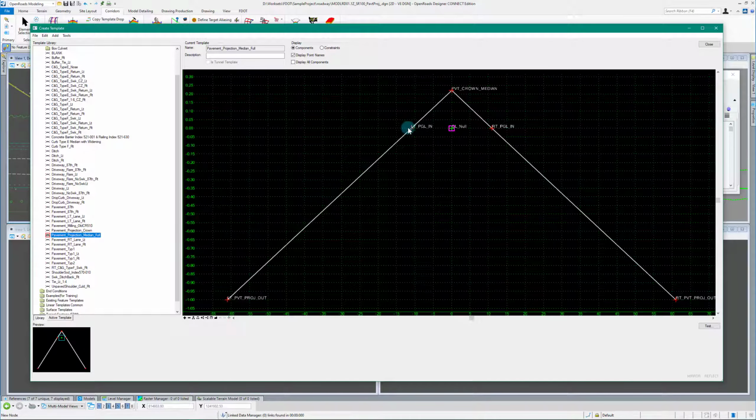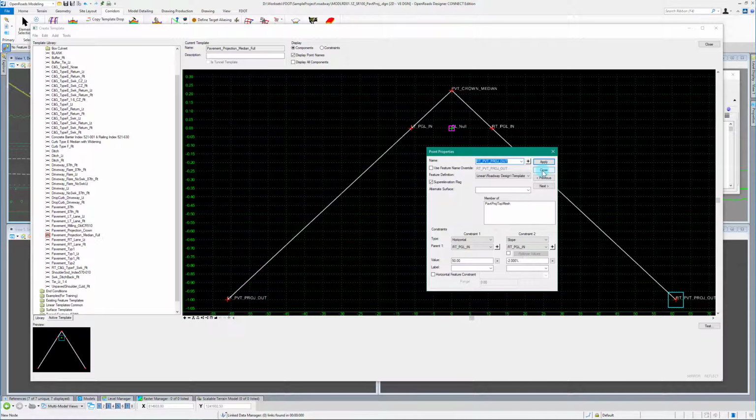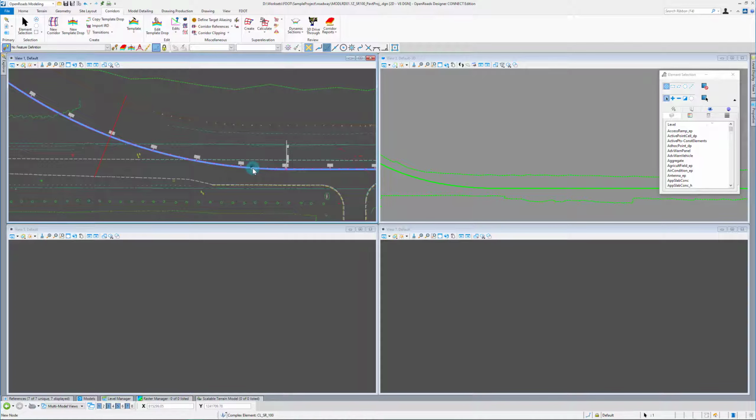And these are also able to be adjusted depending on super elevation. So if I wanted to do that, I could just apply super elevations to these from my super elevation file. We're not worrying about that too much right now. Also, it's creating a median crown, so I'm getting a nice full surface here. So we're going to go ahead and create that.